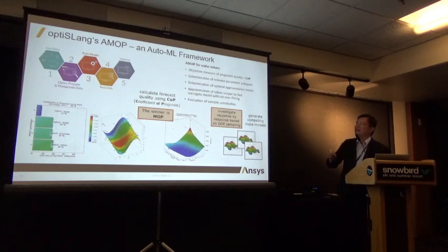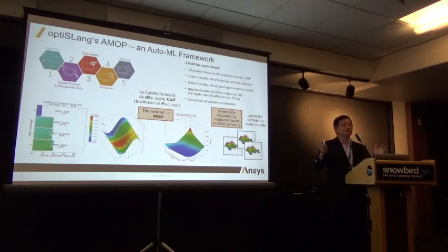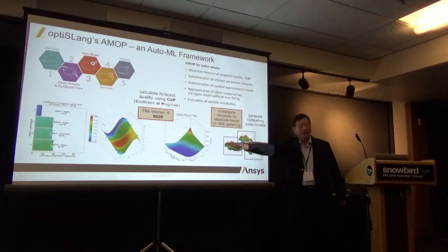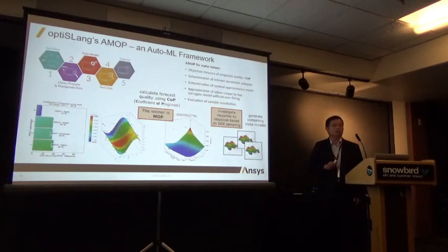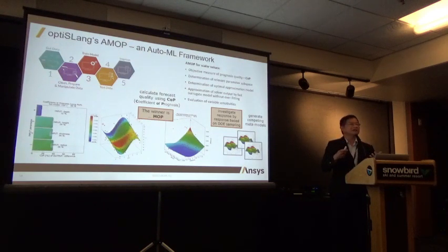Internally, based on the design experiment, we look at the generation of samples. For example, 1,000 samples. We take the first 200 samples to build a meta model, a so-called adaptive meta model of prognosis. We look at the result from the coefficient of prognosis, which is the evaluation metric to see how effective or how accurate the model generated is.